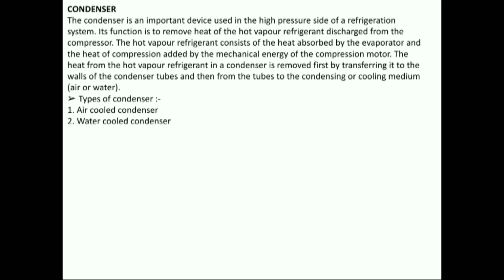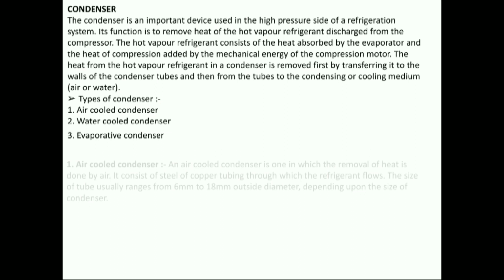Condenser. The condenser is an important device used in the high-pressure side of a refrigeration system. Its function is to remove heat of the hot vapor refrigerant discharged from the compressor. The hot vapor refrigerant consists of the heat absorbed by the evaporator and the heat of compression added by the mechanical energy of the compression motor.